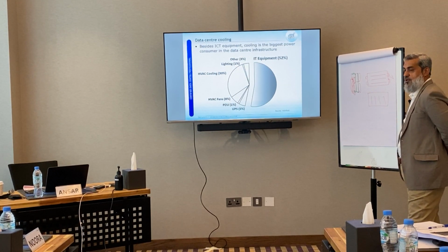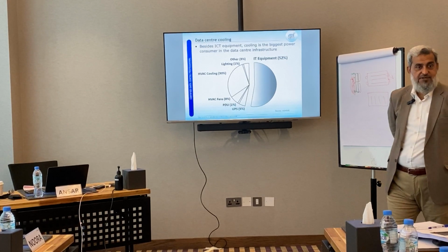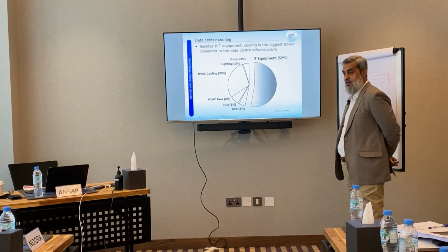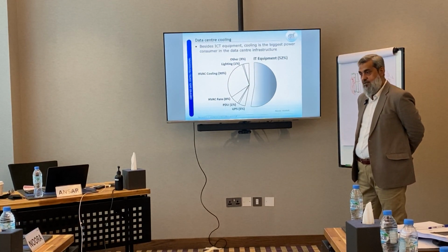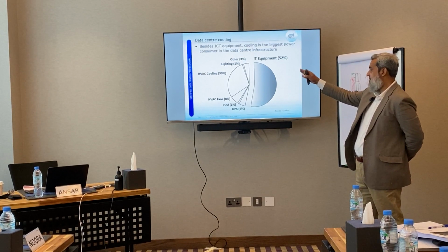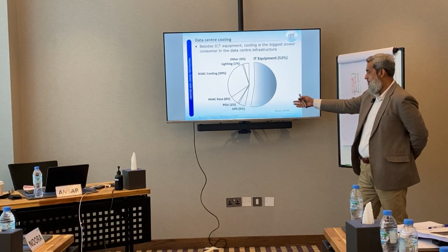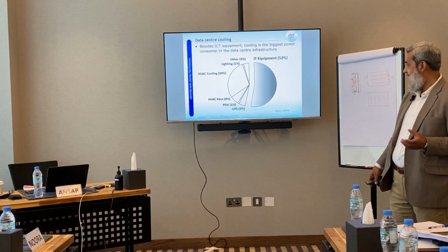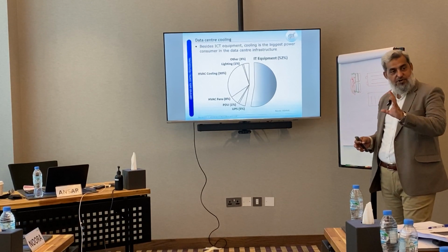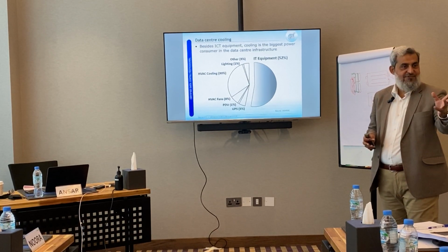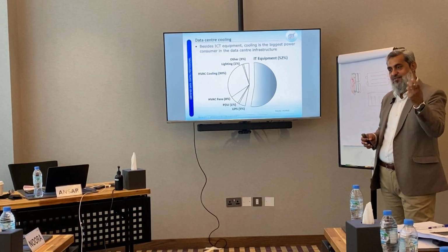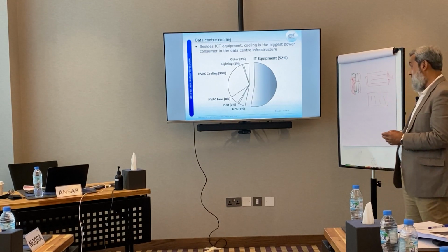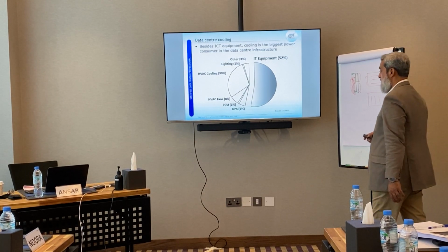So here is a snapshot of typical power consumption in a data center. If our IT equipment is consuming around 52% of the power, then 48% is going elsewhere, like cooling, lights, HVAC fans, PDUs, UPS and all. To produce, basically, 1 megawatt of IT services, you need 1 megawatt of cooling and other requirements to provide those IT services. So it's almost a 1-to-1 ratio, almost 50%.